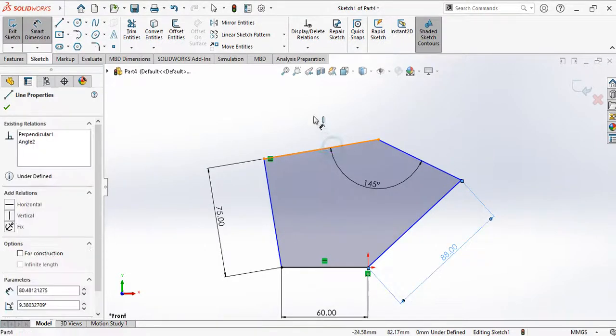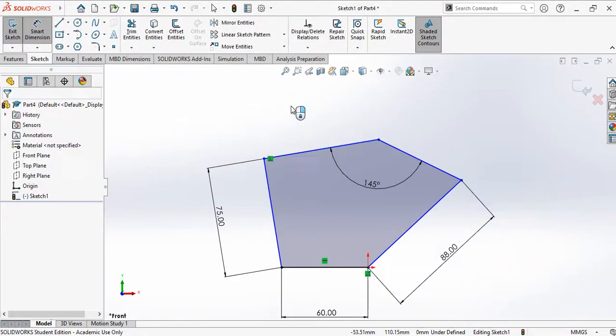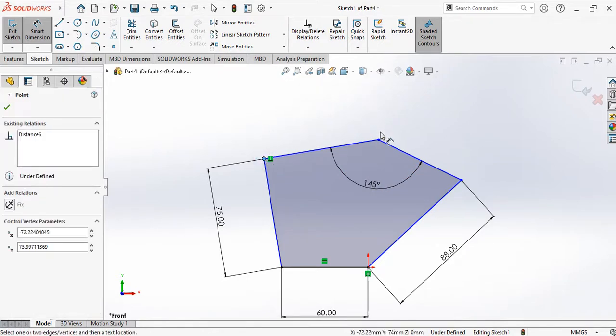And here, okay, besides that, you can place a dimension, just click the line, select the line. You also can select between two nodes. Use smart dimensions, click on the first node, then the second node. It also will appear as a smart dimension like this.